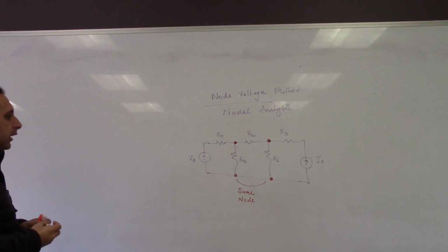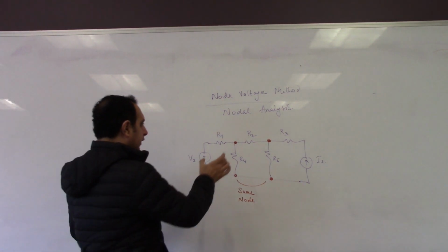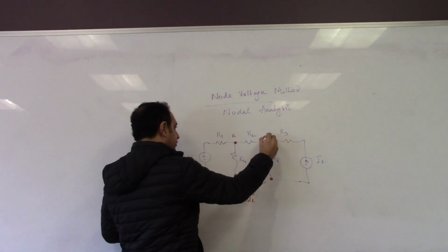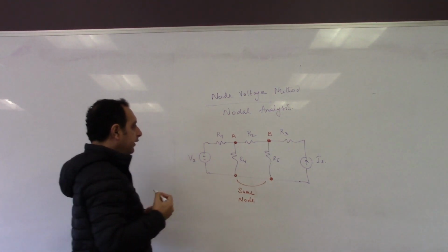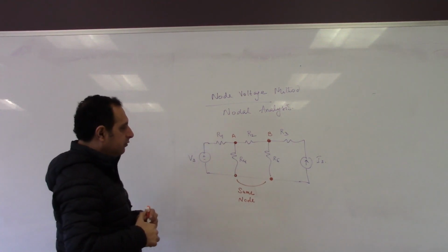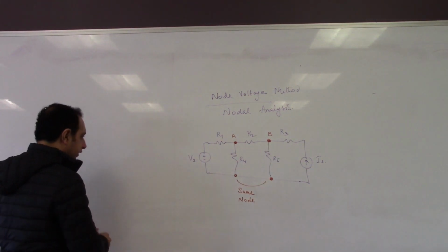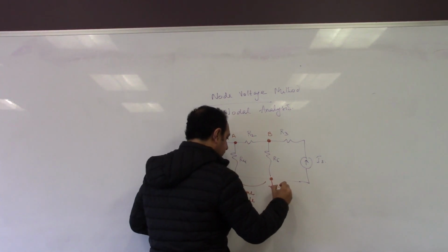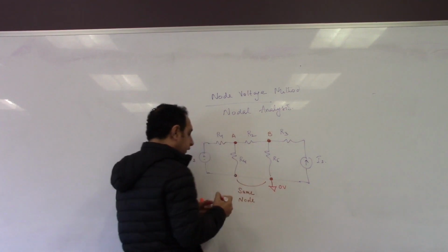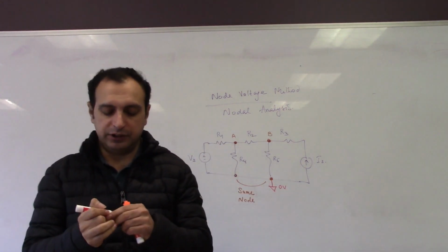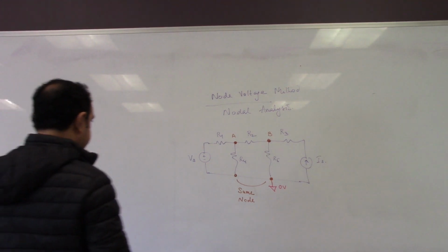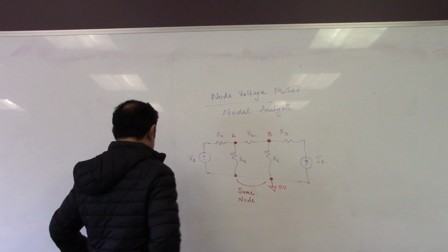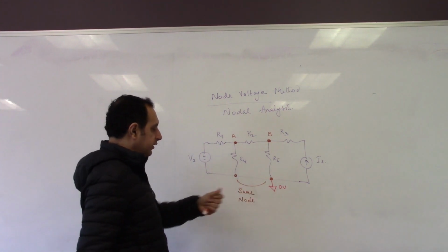Okay. Now what we'll do is, obviously these two are different, so we can refer to them as node A and node B. The last node, just to reference our circuit, we'll mark as our ground. So I'll go here and set this up as a ground voltage. Every node voltage circuit, when you set it up, should have a ground. Only then are we referencing all the other nodes with respect to this.